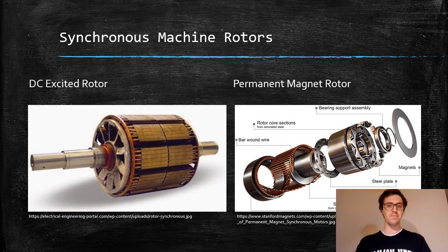Synchronous machines work by magnetically linking the RMF and the rotor. The rotor can be magnetized by either permanent magnets or direct current applied to create an electromagnet in the rotor. In synchronous motors, the speed of the rotor and the stator's RMF are equal, regardless of load. Synchronous machines have no self-starting torque when operating as a motor and need a starting mechanism to work. On the other hand, when operated as a generator, they are self-starting. This contrasting behavior is due to the inertia of the rotor and prime mover and the lack of inertia in the RMF of the stator.